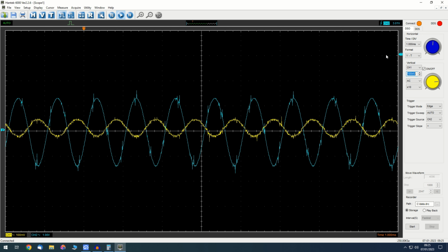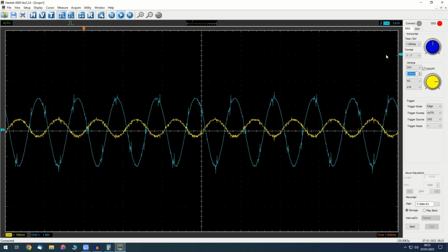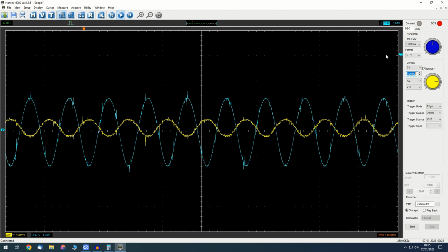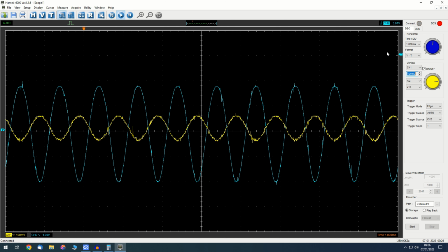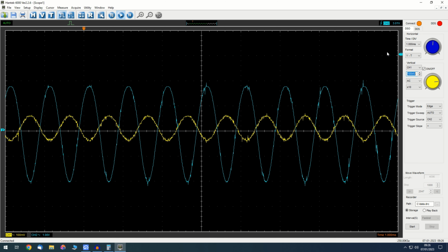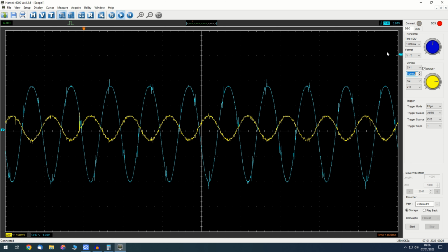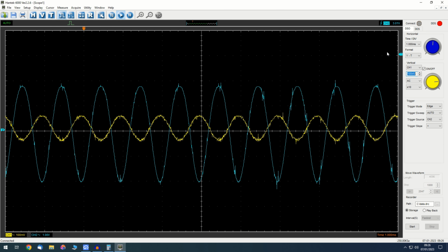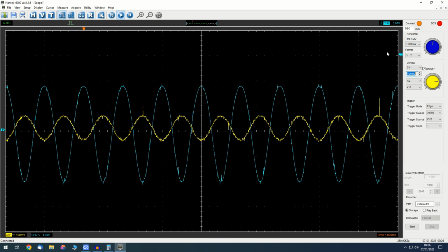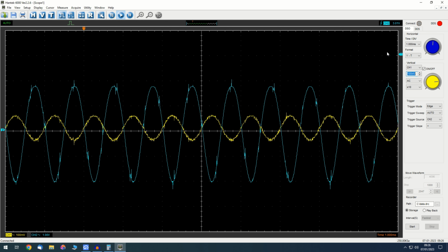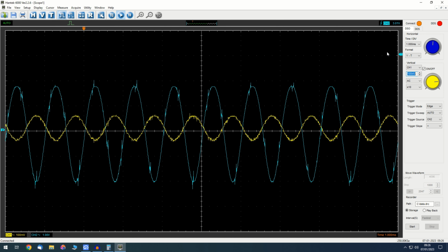and the gain is now looking like it's about 30 or so, 30 to 40 range. It's difficult to see exactly. Yeah, I would say that's roughly 1 division peak to peak on the yellow trace, which means it's about 100 millivolts, and it's near enough 4 divisions peak to peak at 1 volt per division, so it's 4 volts. So the gain's about 40, just from a single transistor stage.